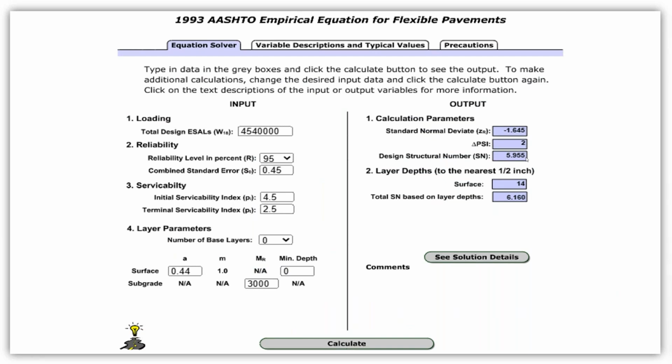But I will caution you, when you look up that nomograph, that graphic is so specific, and a lot of times people will find it in a book and you want to be able to draw on it, so you make a copy. Be careful running things through the copy machine. If it gets skewed or twisted or stretched, that's going to change all of those numbers. And of course, entering it in a computer program is also a little simpler than that. But anyway, those are some ways to get to this number.